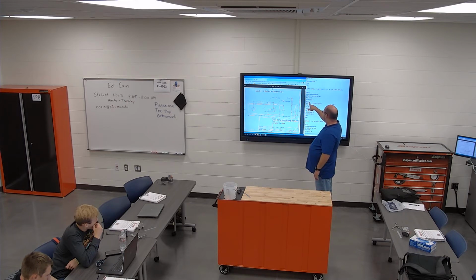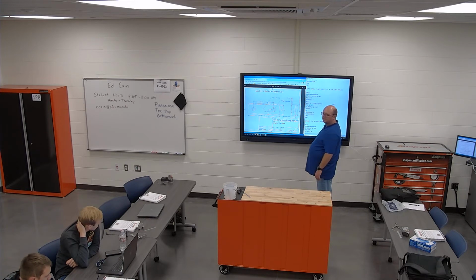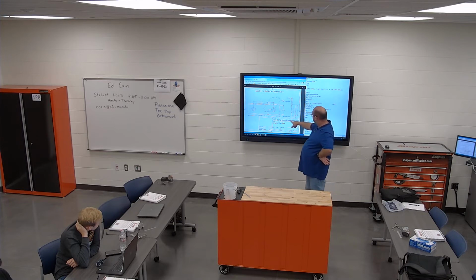So is G43 a rapid move, or is that just the offset? G43 is the offset move, but it'll also move to wherever you put it. Right, and the default is just going to take whatever the machine's feed rate is, and then you put in a code specified. Okay. Now, if you use the same feed rate, you don't have to change it. So Z of 0.1, so you're at 100 thousandths above where your stock was, but keep in mind, we're already down to this 875. So you have more clearance. 125 plus the 100, you're going to be like a quarter inch away.